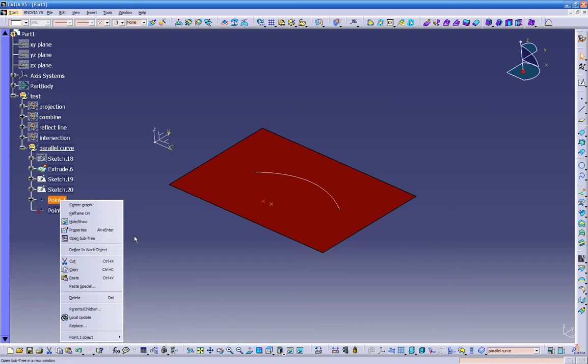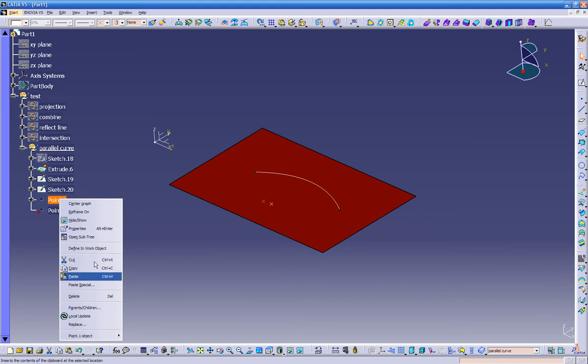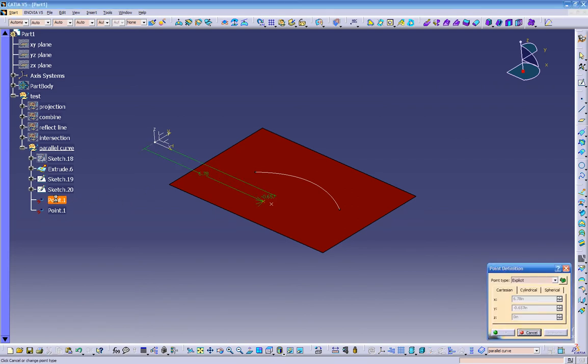So for right now, to break the link, it's very easy. You right click and you go isolate. So if I isolate it right now, you see you got this icon over here. So right now those 2 points are in space. They're not linked to anybody. If I want to do something to it, oh, there you go. It knows what I did, but I cannot edit it.